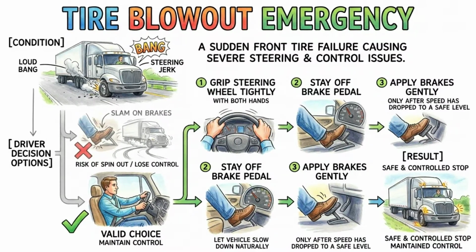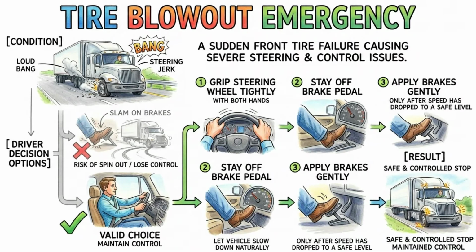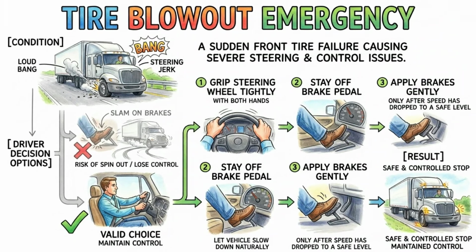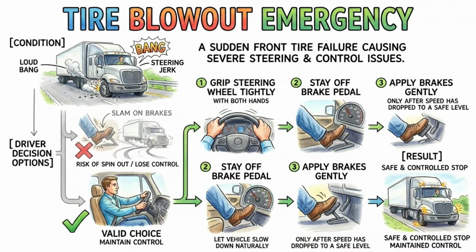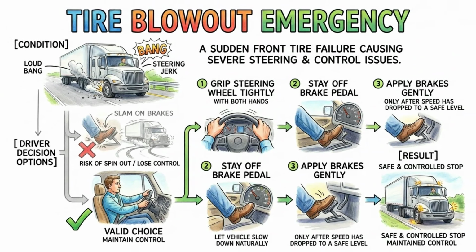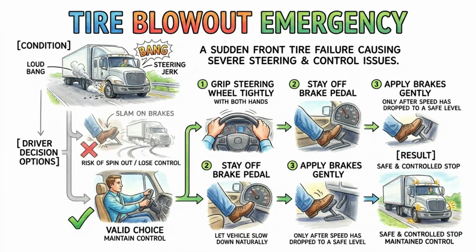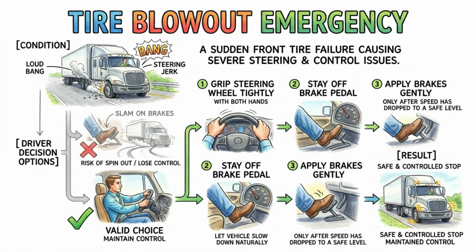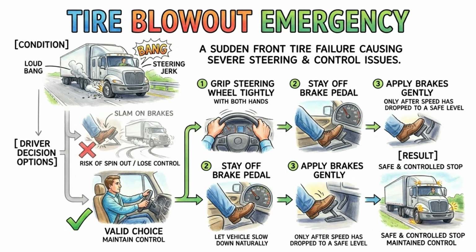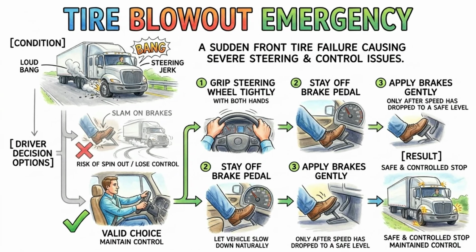Managing the space all around your vehicle is the core of defensive driving. As a commercial driver, you are operating a massive machine that cannot stop or swerve like a small passenger car. You must maintain a cushion of space in front of, behind, and on all sides of your truck. We discussed following distance previously, but you must also be highly aware of the space above your truck. You need to always watch for low-hanging tree branches, unrated bridges, and low power lines that could strike the top of your trailer.